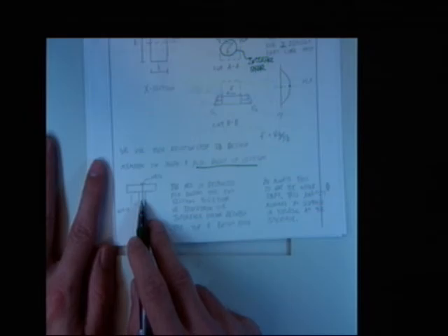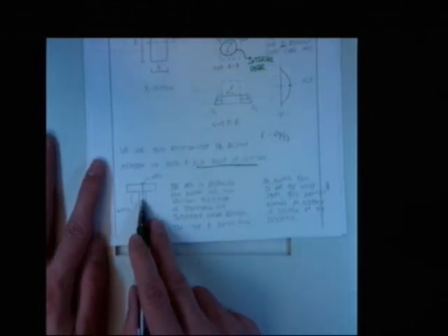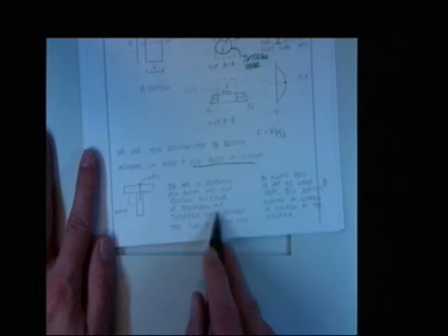So we use this relationship to design members in shear, and we also use this same idea with a built-up section. Same concept. And you've seen this before. You've worked problems previously where you had two pieces of wood, you had a nail, and there was a beam in bending. And you wanted to know how big the nail needed to be and how close it needed to be spaced. Usually they gave you the size of the nail, and you picked out how close the spacing had to be. And we're going to work this exact same problem in this class. It's going to be exactly the same. We talk about interface shear. The nail is responsible for holding the two sections together, or transferring the interface shear.